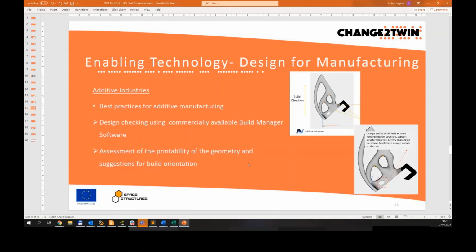Then here we do the design for manufacturing. So basically, we consider the product manufacturing requirements and constraints during the design stage itself. It's mainly required because when you consider additive manufacturing, different printers have different requirements or constraints with respect to thickness, build orientation, the minimum thickness requirement, porosity, etc. So we try to include this information even during the initial design time, so that it is easier to get the whole design done and it doesn't go into an iterative loop.